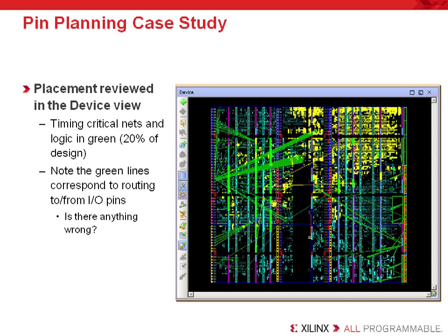To fix this, it will take the tools a lot of implementation time and effort, but the better solution would be to move the poorly assigned I/O pins, which may or may not be possible depending where you are in the design flow.